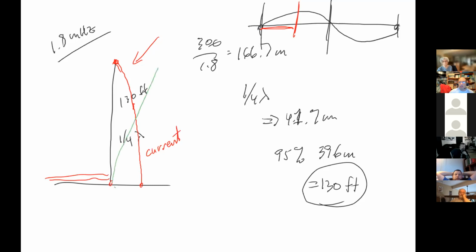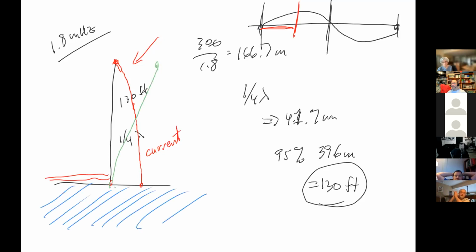But where's the rest of the antenna? Where's the rest of the antenna? Coiled wire? Part of it's missing. Where is it? Ground plane. So what actually exists is that there is a reflective surface, which I'm going to draw, which represents the missing other half of the antenna. So this quarter wave antenna has to have a ground plane.